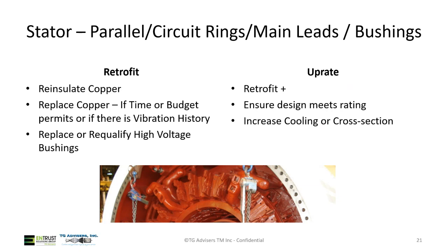For the uprate, just like everything else I've talked about so far, it's a retrofit plus a few other things. If you are going to keep your design or the conductor, you have to make sure that it's going to meet the new rating. Meaning that if you have the same length core and you're not changing the voltage on your machine, there's going to be more current going through all the components. So if you get an uprate and you don't change your voltage, you're going to have more current.